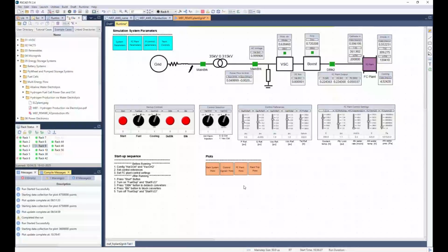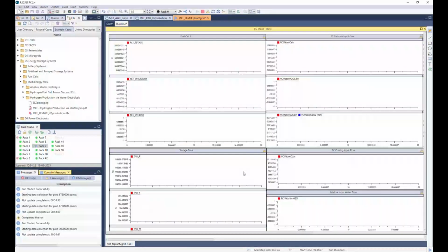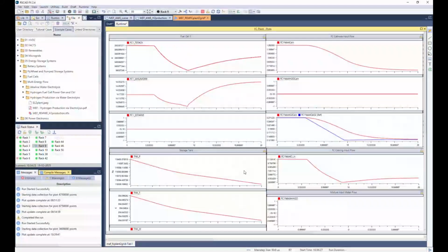You can see the plant waveform inside this hierarchy box. As the fuel current drops as a result of the reference change, the consumption of hydrogen and oxygen also goes down. Fuel controller adjusts the fuel delivery rate to the stack to keep the utilization factor steady. This is why you are seeing this reduction of hydrogen and oxygen to the stack.